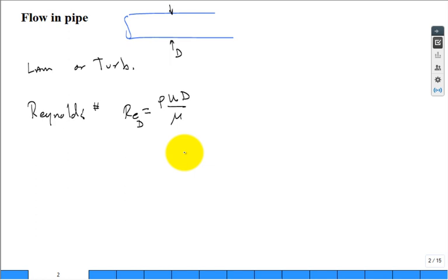It's the inside diameter that the fluid flows through. Okay. Little question here. Sometimes they'll put a little subscript m on that u sub m. What is that? It's a mean velocity. It's a mean speed. It's the average speed, because we know that the fluid flowing right next to the wall of the pipe, because of the no slip boundary condition, it's really not flowing. You have to move a little bit away, but in the core, in the middle of the pipe, it's flowing the fastest. So near the walls, slow. In the core, fast.